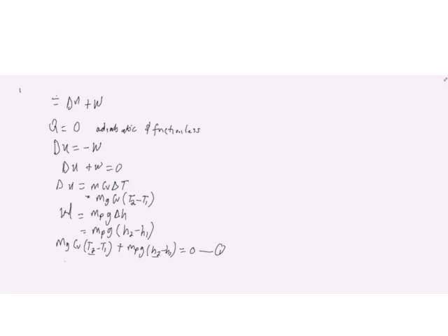So again, we have our ideal gas equation. Since the gas is modeled as an ideal gas, we have PV equal to mRT. Here it's the gas we're looking at, so this is the pressure of the gas, this is the volume of the gas, and this is the new temperature, with pressure P2. This implies that the new volume of the gas is the area, which is constant, multiplied by the new height of the gas.